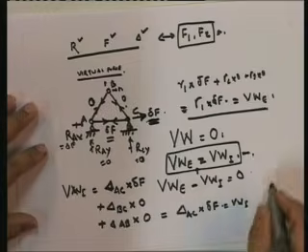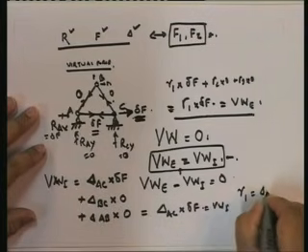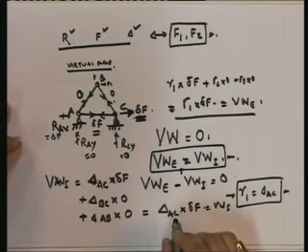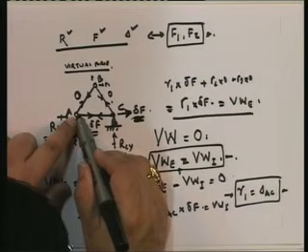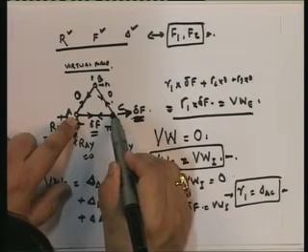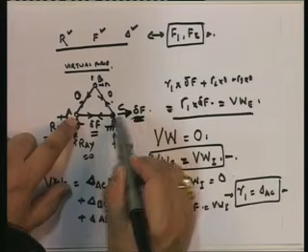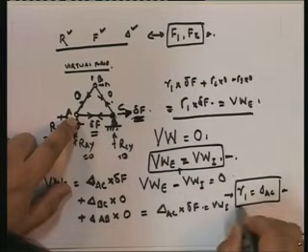If I equate the two, what do I get? You will see that R1 is equal to delta AC. This is what you get. Now this is not surprising. Let's go back here. This point is not moving anywhere. Now, how much does this move by? Well, it moves by whatever is the actual deformation in member AC. So that's what you've got.